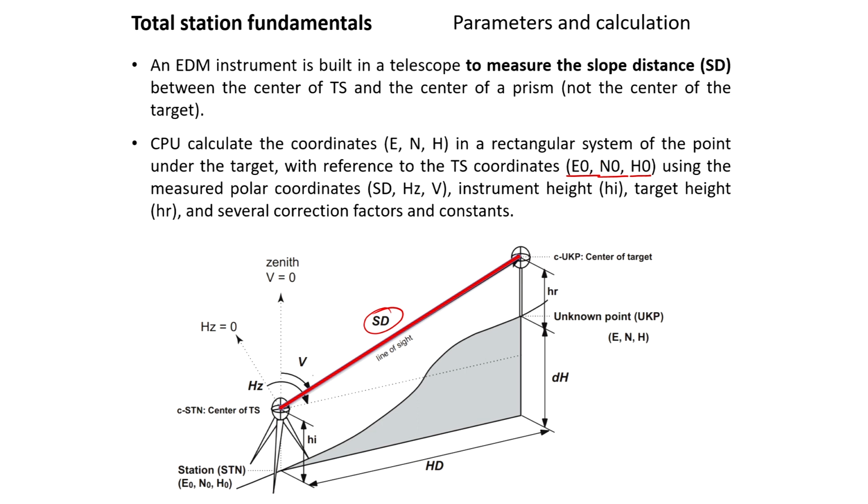Okay. Now, there are a few more things which we usually do. As soon as the station has been established, we take what we usually call the back point, the backside point, to have the reference, and then we start our measurements. This part we will try to explain to you in the actual lab, which we are going to perform on the ground. This will help you further understand what exactly we are doing and what we are measuring.